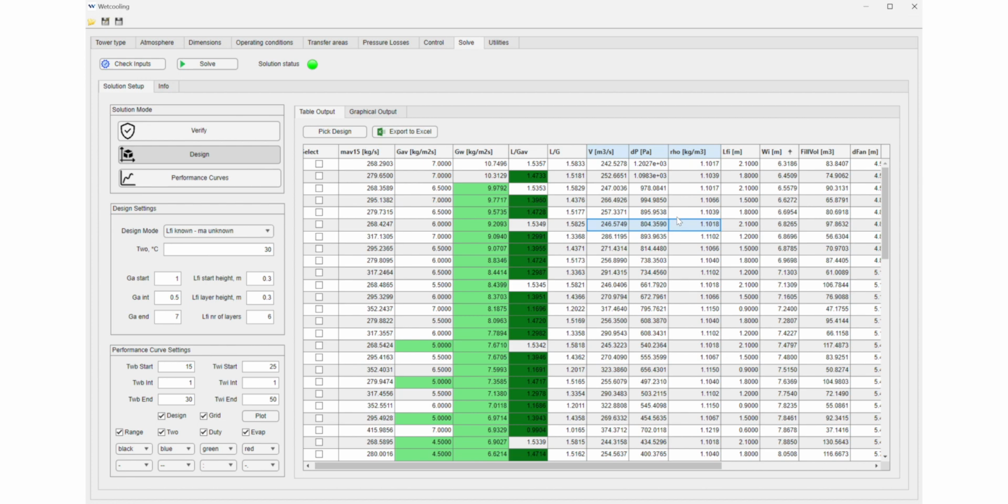Then you can get the characteristic curve. You can enter the characteristic curve into the fan tab, and then if you rerun it, you can see if you get the same operating point as predicted by using the fan curve as well, in verification mode.